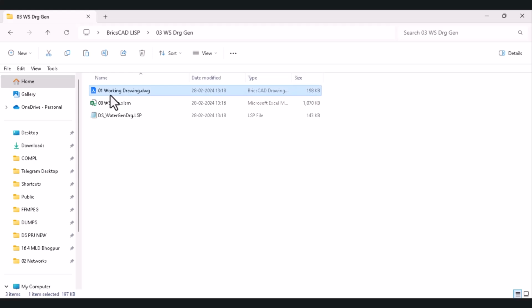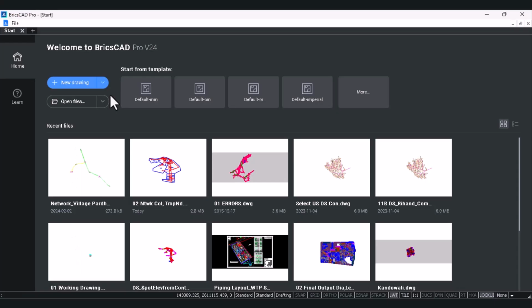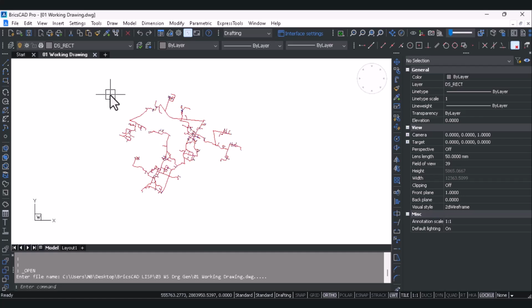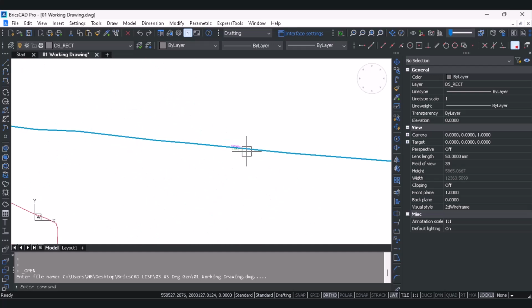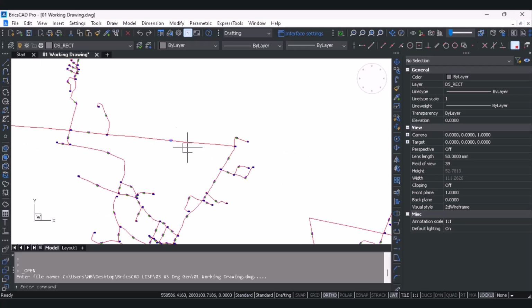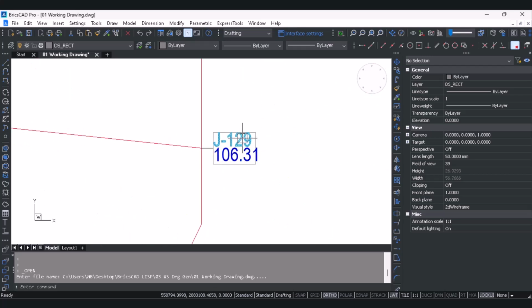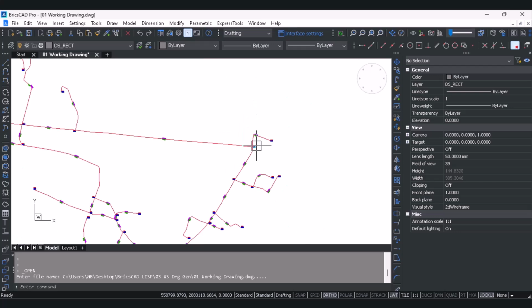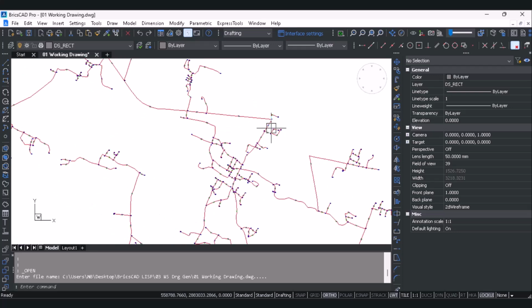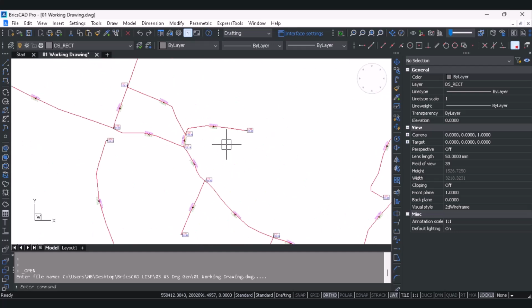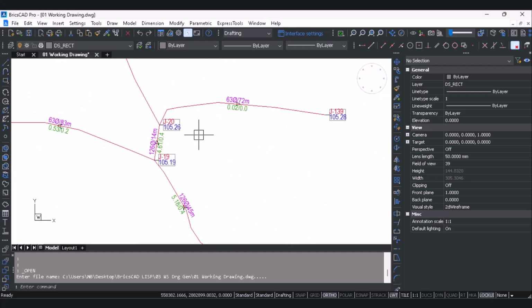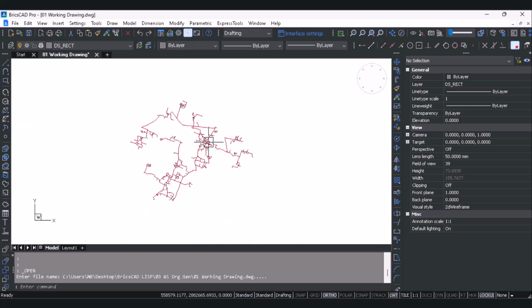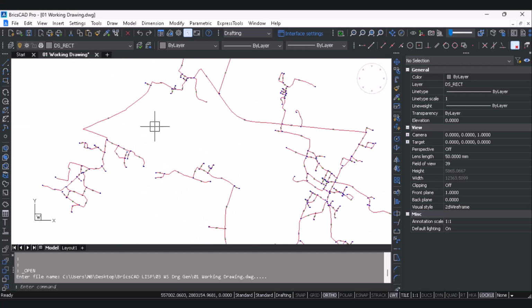Right now what people do is that they generate the DXF file from any software like WaterGEMS or SewerGEMS, and then there is a lot of text overlapping, and then they correct the text overlapping manually. Like we have to write the pipeline diameter and length at every pipe, and also at the junction we have to write the junction label, the elevation as well as the pressure. So we have developed a LISP functionality wherein the placement of text is automatic, so that there is very minimal overlapping which the draftsman needs to correct manually. Otherwise, almost 99% there is no text overlapping.